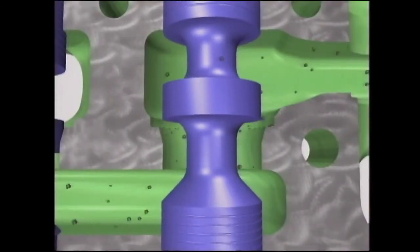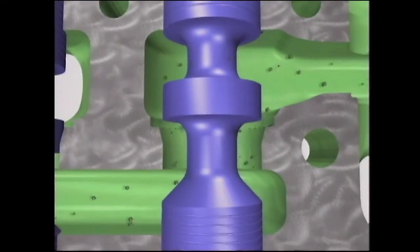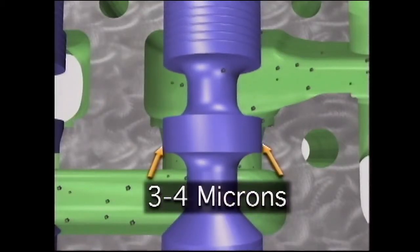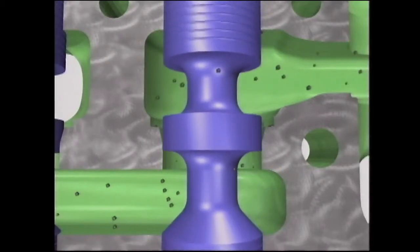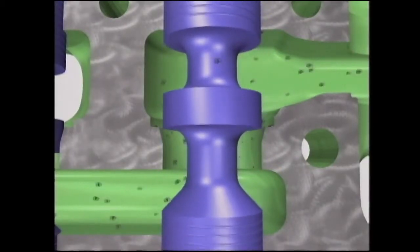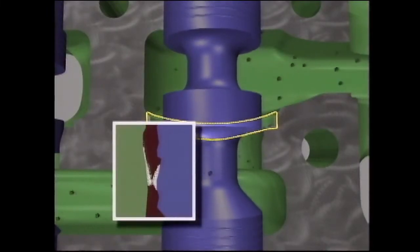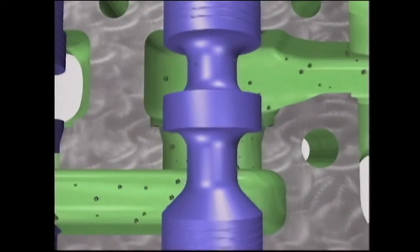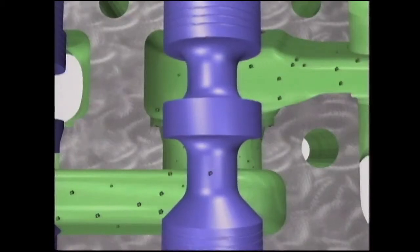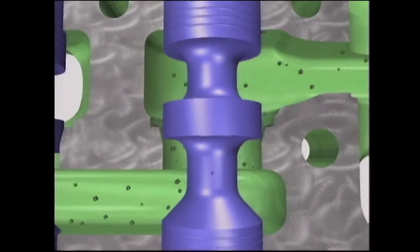Electrohydraulic valves are more susceptible to contaminant damage because the clearances are even smaller, as small as 3 to 4 microns. Some of the particles naturally adhere to the imperfections in the wall or because of the electromagnetic conditions in the valve. This buildup, or siltation, can either slow the spool, causing sluggishness, or make the spool hesitate, causing jerkiness in the system. Over time, the contaminants can cause wear on the spool that results in leakage, and sometimes a large particle can become lodged and block the motion in the valve.